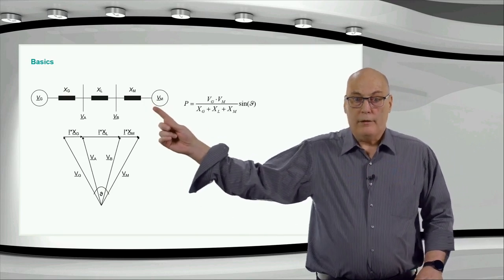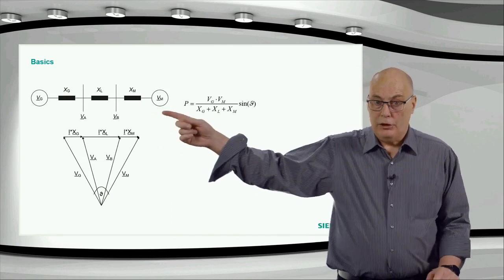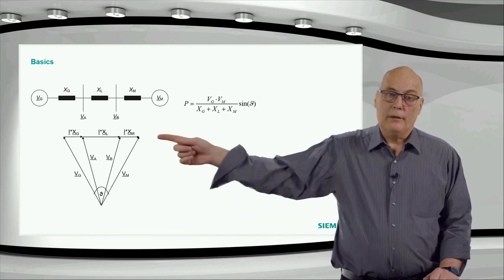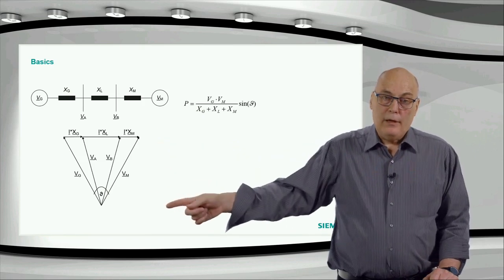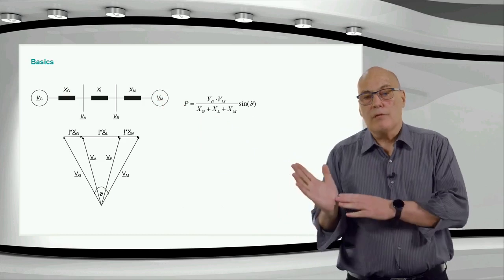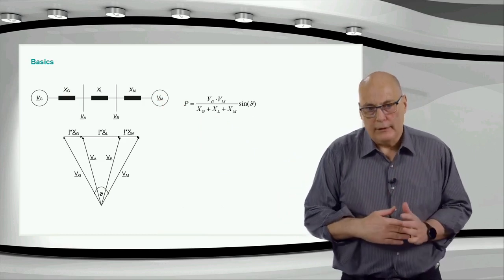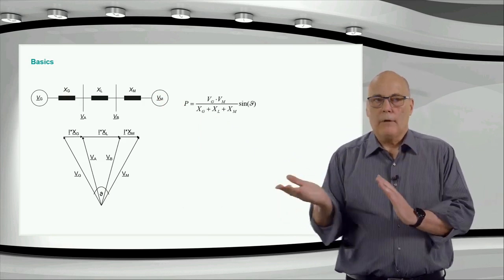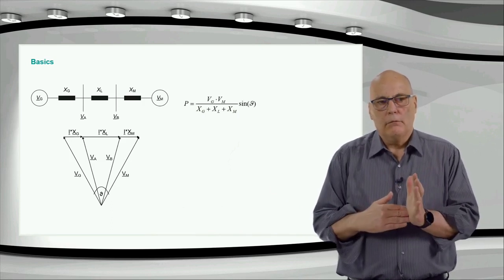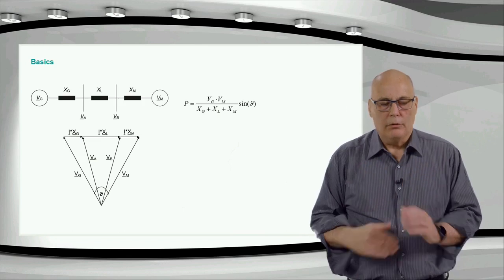There's only one current in this system. There are no other shunts. It's flowing from the generator to the motor. That's the current, and this is the current shown here. And because that current is vertical, in these reactances it causes a voltage drop which is 90 degrees. Current in a reactance is going to be lagging the voltage. That's right.